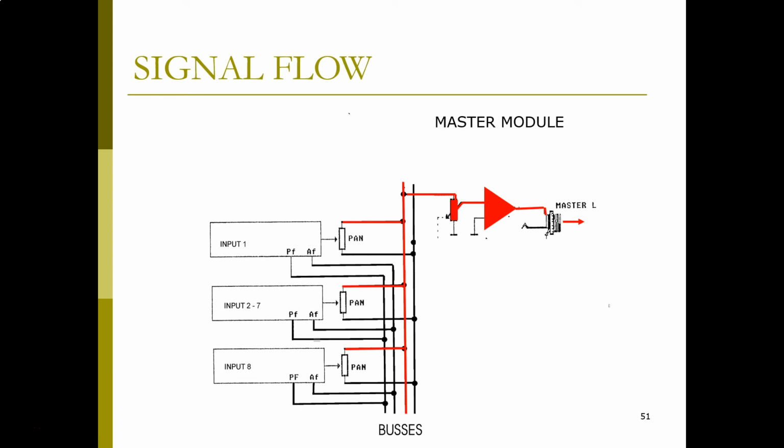potentiometer, which is the master level for the left channel. Then there is the amplifier, which is the buffer amplifier for the left output. The same thing for the right output with its own fader, and the dotted line between those two indicates that both of those faders move together. There aren't, in this particular case, separate knobs. They are 2 different potentiometers or faders built into one unit.